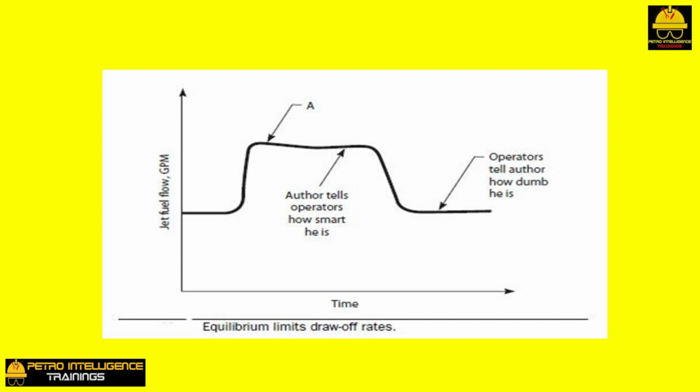What happened? The problem is equilibrium. When the pressure in the tower was raised, lighter components from the vapor were forced to dissolve in the pool of liquid in the draw-off sump. This meant that, at the new equilibrium conditions, the lighter liquid would boil not at 10 psig but at 14 psig.